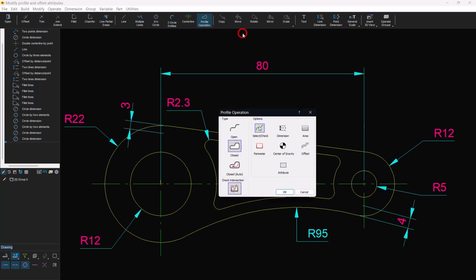In the closed contour, when there are vertices with more than one line, the user must identify which line to continue the contour. With the Auto-Close Contour option, you identify the line inside the contour and the function searches for the contour automatically. The Check Intersection option looks for lines that intersect the contour, not just at lines' endpoints. In our case, the contour lines are connected at the endpoints. Do not select this option.